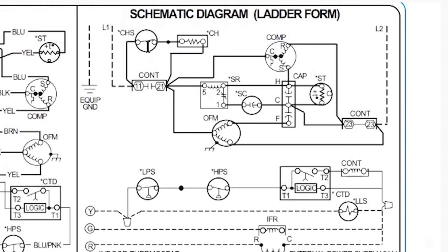So I know it's temperature sensing because of what it looks like down below the switch. So this is like a connection point here, and the fact that it's closed means that it's normally closed. So under normal circumstances, it's going to be closed. Usually that's with no power applied. And then if the temperature increases, it's going to open. These schematics are all designed to be read from left to right, like reading a book.